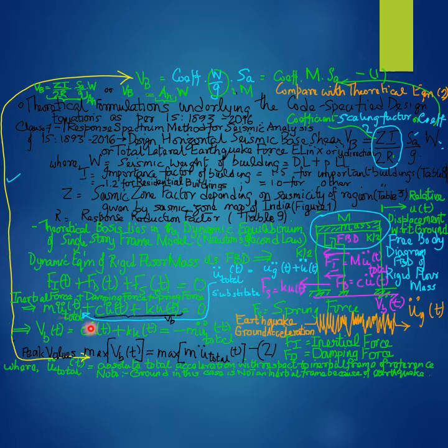The reason that the subscript total or the notation for the acceleration of the floor mass is adopted as u double dot subscript total is that the ground, which is the frame of reference for measuring the relative displacement u in the horizontal direction of the floor mass M, is not stationary, that is not at rest, but is also subjected to a motion, that is the earthquake ground motion, represented or modeled by an earthquake ground acceleration time history.